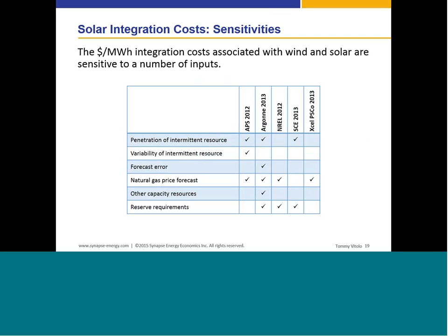A couple of folks looked at reserve requirements again, and I think it's important to think about reserve requirements, and I hope that the larger regulating authorities continue to think about it. As we have more intermittent resources, maybe our traditional reserve margins aren't the right way to think about it. And maybe we do need to have a reserve margin that is a function of the amount of wind and solar on our system and the way that it tends to dispatch in our system. So there's plenty of room, I think, there for really studying reliability.